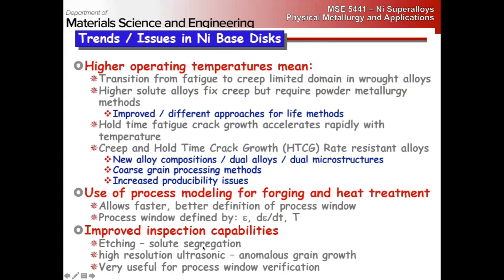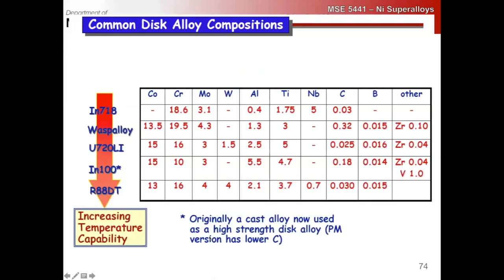Particularly high-resolution ultrasonic. People are doing all kinds of stuff with backscattered ultrasonic now, where they can measure the grain size by looking at the backscattered signal, which is normally just considered noise. But these are things that need to be considered.